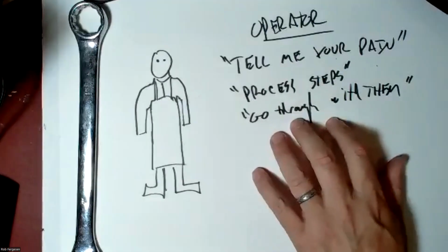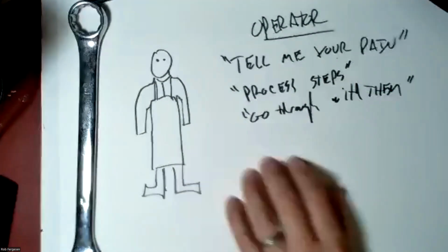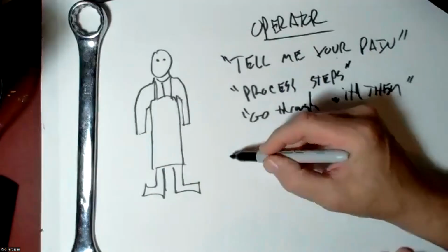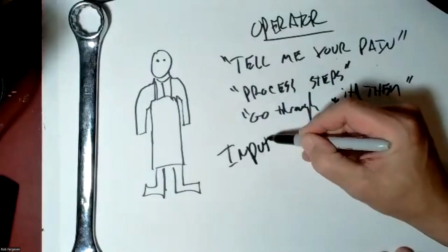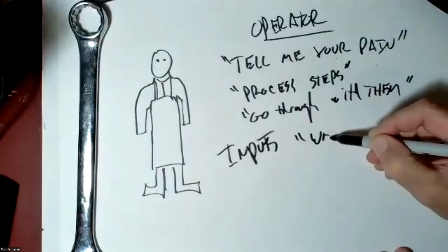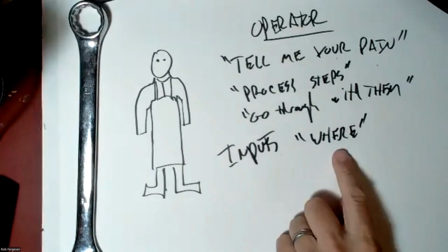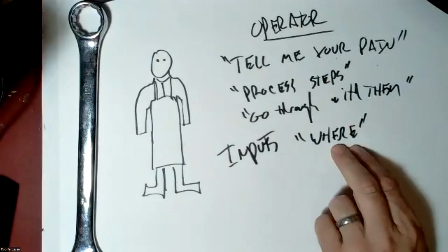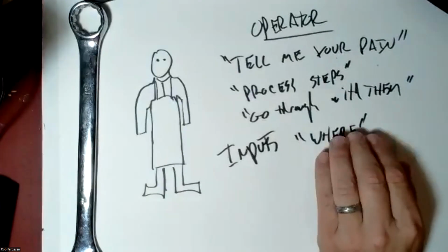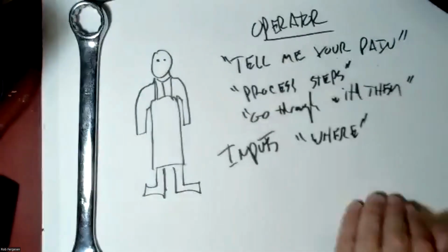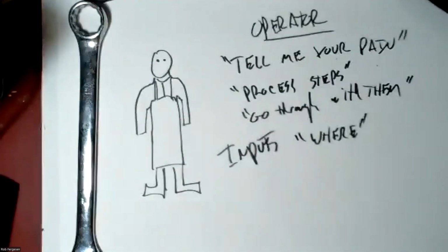Then you're going to be like, all right, where do you get your parts from? So your inputs. And they're going to show you where they get their parts from. They say, oh, I got 4 types of parts. And you're like, 4 types of parts. That's really important, because that means I might need 4 different vises, or I might need 4 different programs for my robot. The parts are all aluminum blocks to start with, and they're all just stacked on a table to start with.